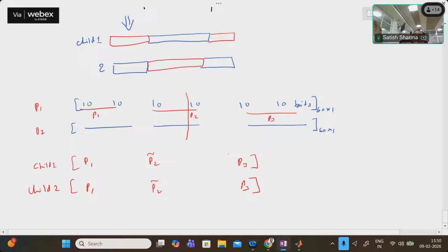For economic load dispatch, gradient is the best. You don't need a GA for that. GA is not good for economic load dispatch; we can simply take the derivative. There is no non-linearity, so we should not use a genetic algorithm for the economic load dispatch problem. It's a very simple problem, unless there are multiple objectives or discrete variables where we cannot take derivatives.